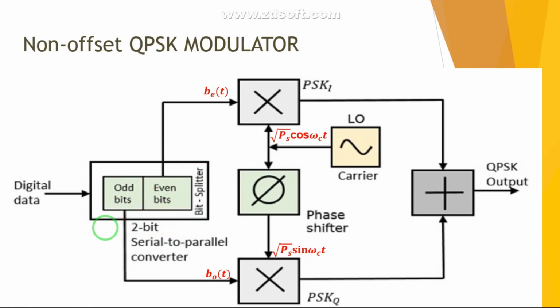So this amplitude variation can cause difficulties in your QPSK communication system, which employs what, repeaters also, because it is a long distance communication, so it may have repeaters also. And as we know, generally the repeaters operate non-linearly.